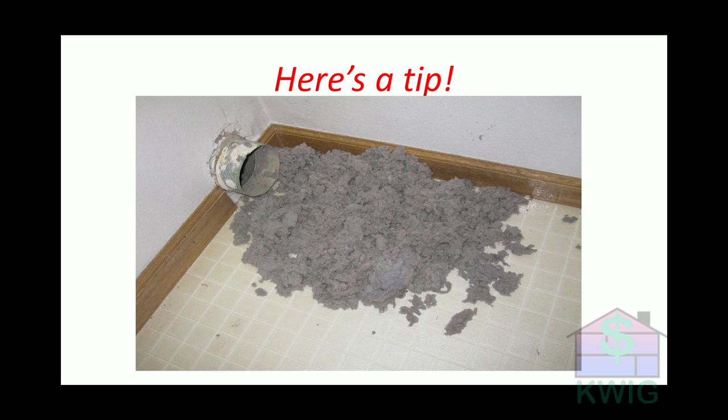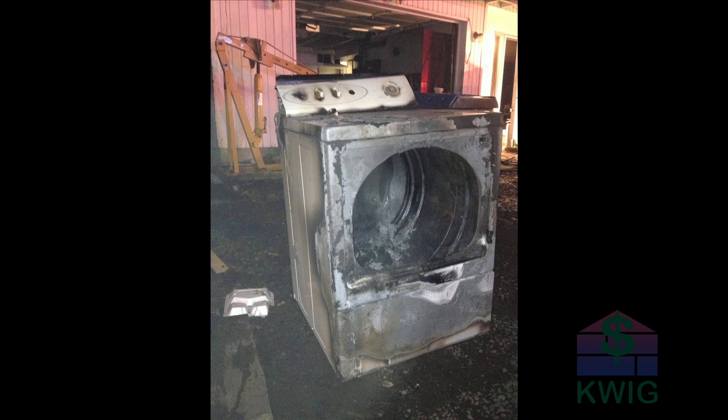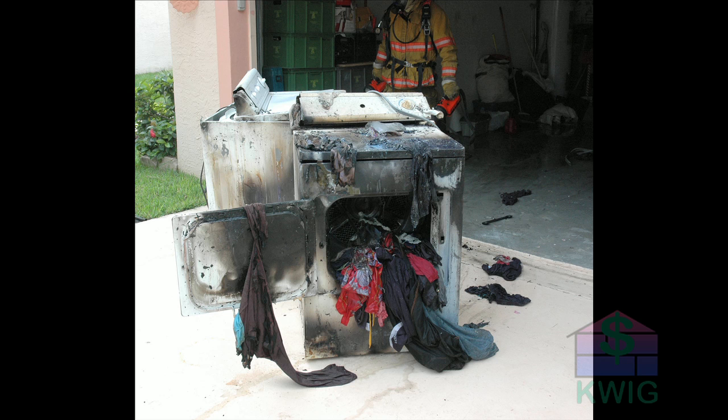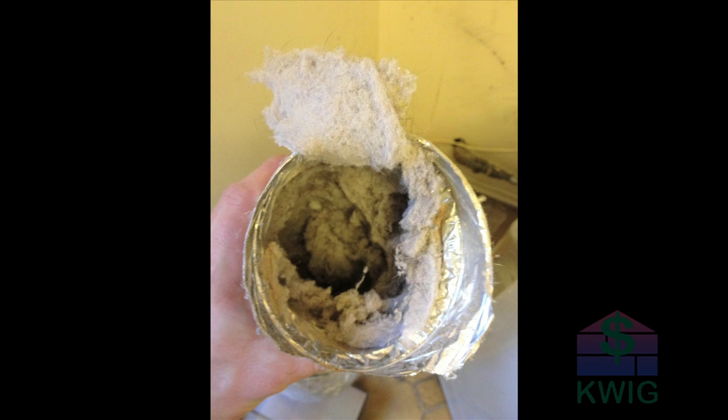Here's a tip. Have your dryer vents inspected and cleaned out annually to prevent clogs, which can lead to house fires. The lint trap on your dryer only catches about 70% of the lint. The rest exits through the vent tube. But some of that will adhere to the moistened walls of the vent tube, and over time it will build up.